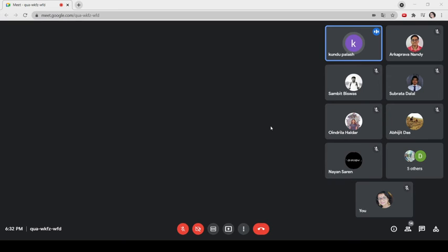Now the timer value for the required delay can be calculated as below. The time delay will be the content of the timer count registers, either in the form of 13-bit or 16-bit, multiplied by the tick. That means one count will produce a time delay of one tick. So the register value to produce a given time delay will be calculated according to the timer maximum minus count, and this is the formula. According to the formula, how much binary value in 16-bit or 13-bit you have to load will depend on the count register. So for a given time delay generation, say 6 microsecond or 1 millisecond, the timer data registers can be calculated.